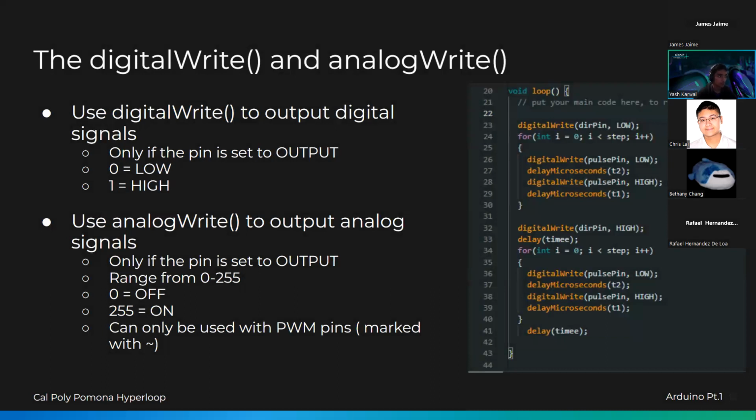One thing to note when you hook things up though, these pins are rated for about 40 milliamps of current. So one LED is fine on one pin, but don't put 3 LEDs, because one LED takes 20 milliamps to run. So 3 of them will take 60, which is more than what the pin can supply, and that could cause a problem or a fire, depending on how much current you're drawing, or just the whole thing turning off.